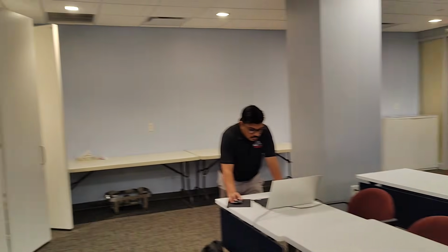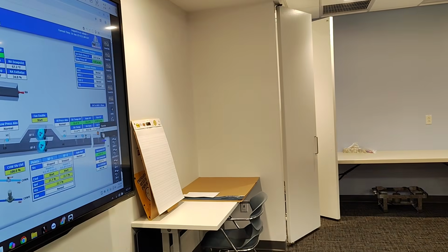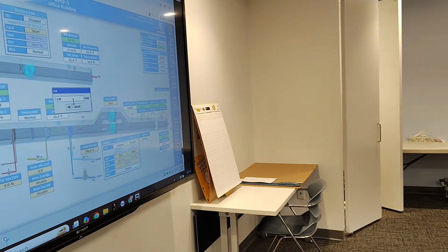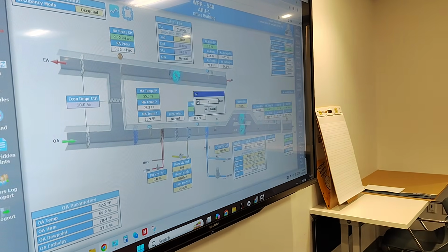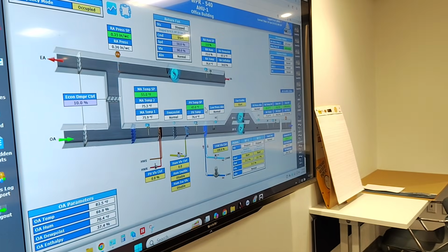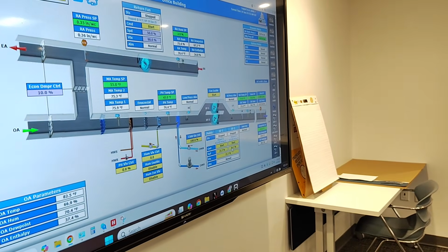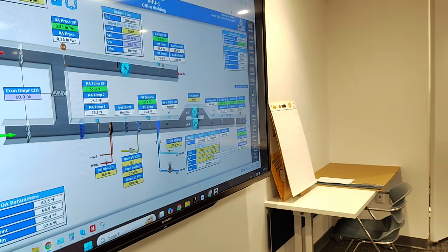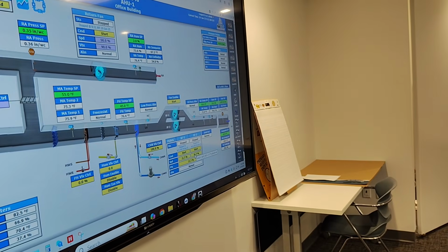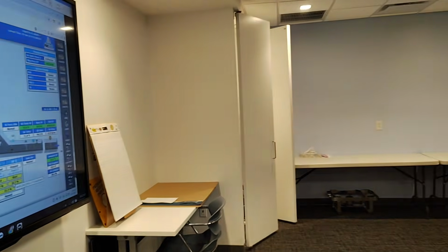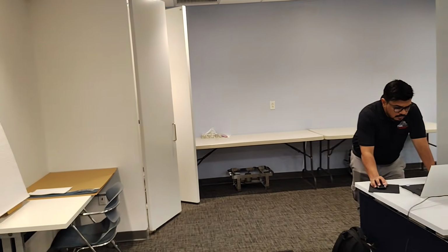Now, put the static pressure set point back to 0.9, because that's where they want it, that's the spot they used to change the static pressure set point for. Now, I'm going to explain a couple things about AHU1 after I have him do some stuff. Now, put the fans up to 0.9. Oh, they did move. They were down to 0.23. They were 0.24 before. No, it was 0.19. 0.12. Go back to 2 inches and let's see what happens.